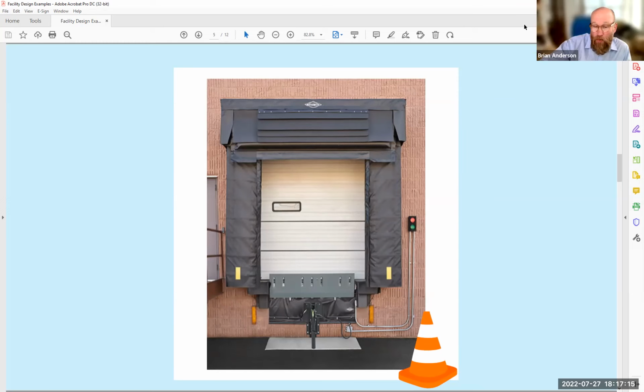Go ahead. So this is one that I like. The bottom of that door is a horizontal, sort of lighter gray bar with some lines in it. That's an exterior mounted dock leveler. I like exterior mounted dock levelers because they don't create an air infiltration hazard to your sill. Think about where that rolling door lands, right? That should be a nice tight air seal. When that rolling door is closed, that's your protection against infiltration from everything outside getting inside, right?